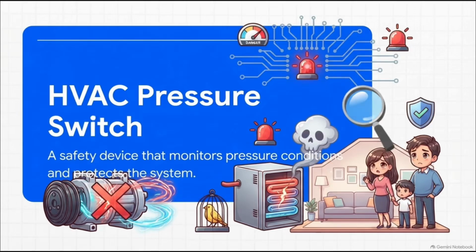An AC compressor can tear itself apart internally if liquid refrigerant floods back, or if head pressure goes astronomically high. Over on the heating side, a furnace heat exchanger could end up pumping lethal carbon monoxide right into a family's living room if a proper draft isn't established. This little component is your absolute ultimate fail-safe against those kinds of disasters.